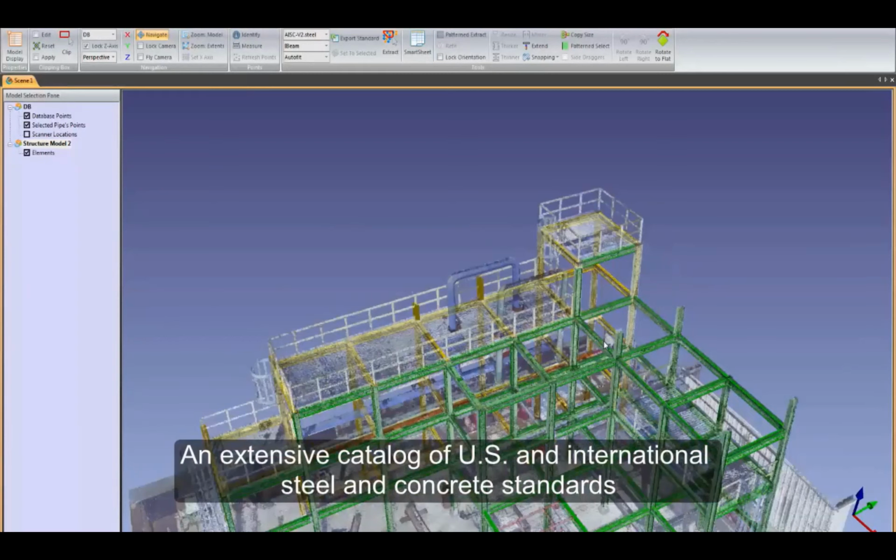I hope this helps. Claudio would like to know if it's possible to combine data from two devices when you're in a large building? Yes, and if we are talking about two different laser scanners, it may be possible to a certain extent, depending on the parameters. For example, in the GLS 2000, the data can be automatically georeferenced.